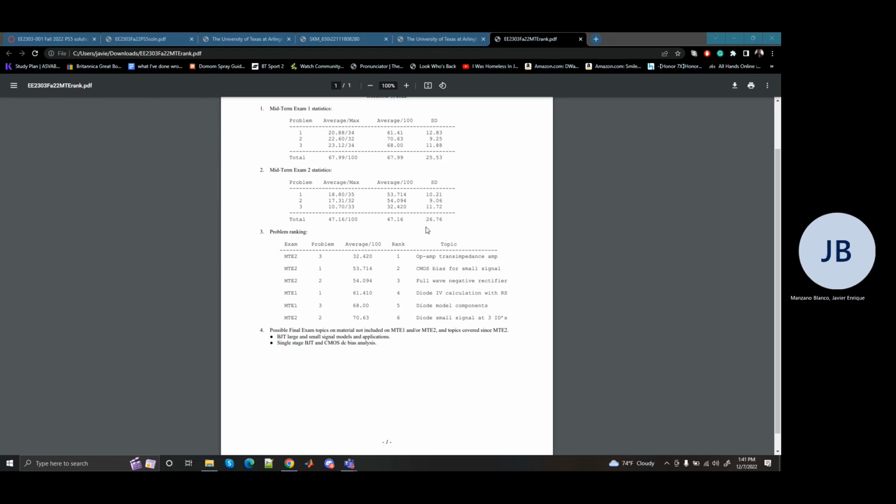So don't be scared of the capacitors. They exist for a reason, and that reason's relatively simple. You want to use the DC case to get yourself at a level where this will operate the way that you need it to. And then you can introduce AC, some signal that's changing, some signal that you want to amplify, by blocking any DC changes to this, but the AC signal is being let through a capacitor.